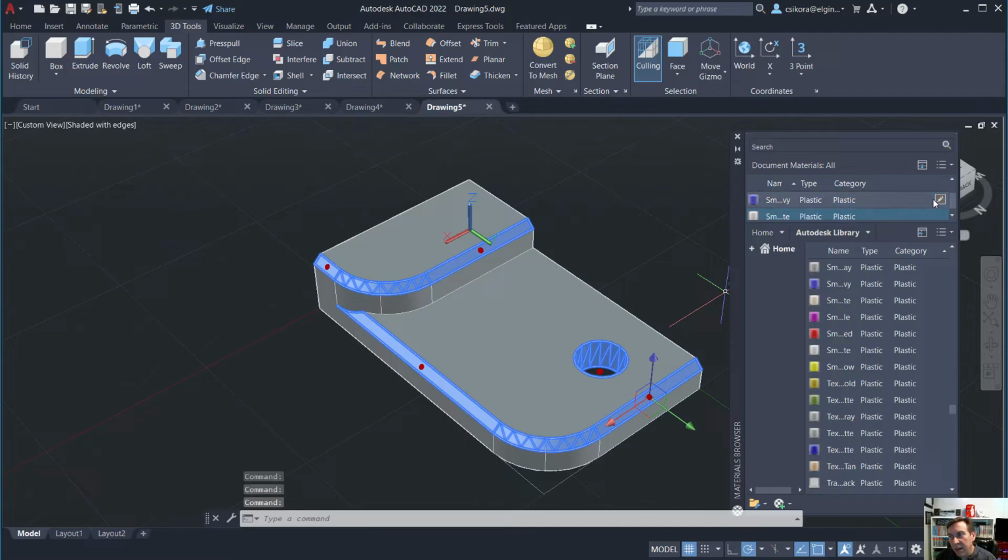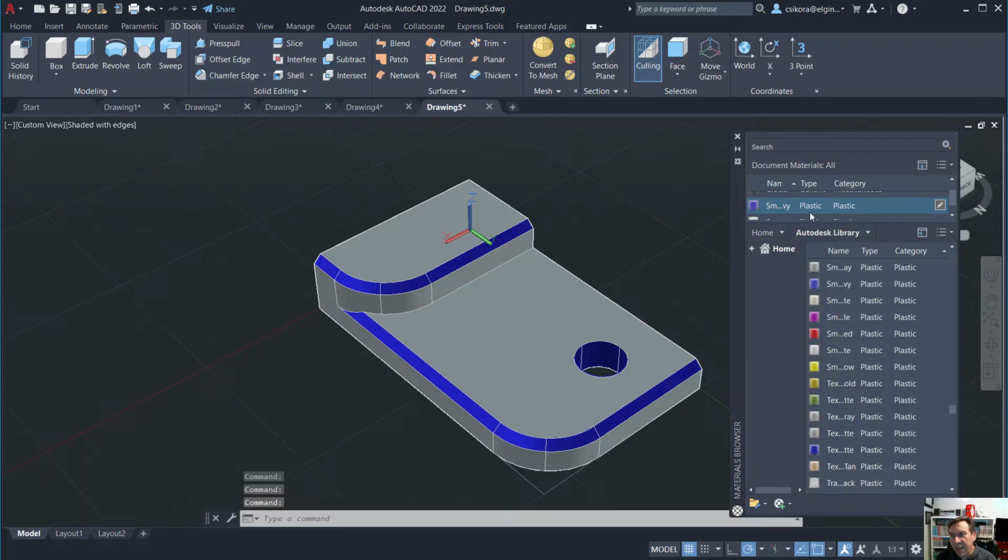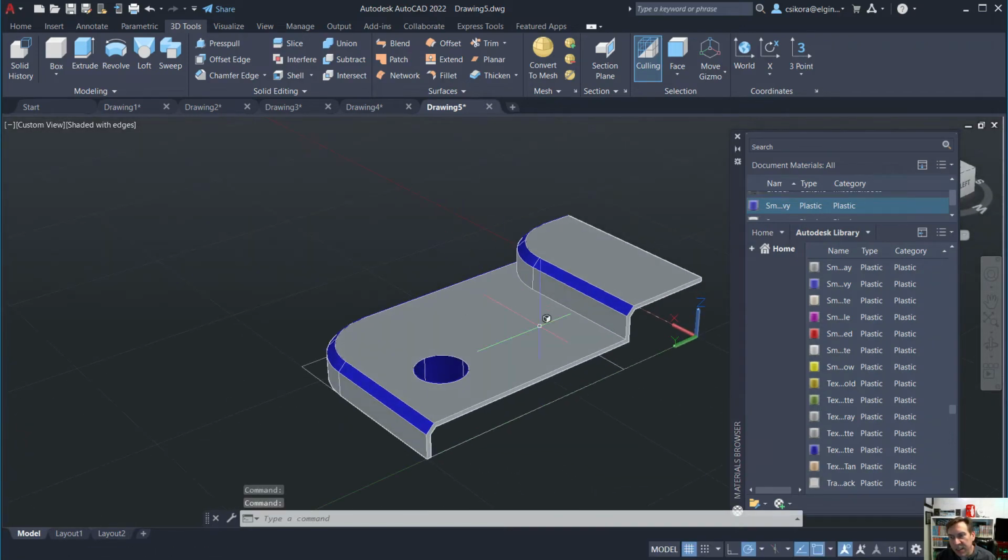And now over here, you could do it by clicking right on the actual entity there, or you could just hit the little arrow up and it will add it too. You could pre-select, post-select, so there's a number of ways to do it. Let's try that one more time. Let's say we want this edge to be highlighted like it's a cross-section, either red or yellow. Go ahead and pre-select that face.